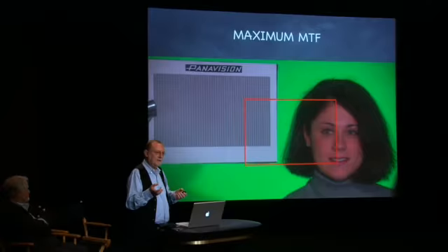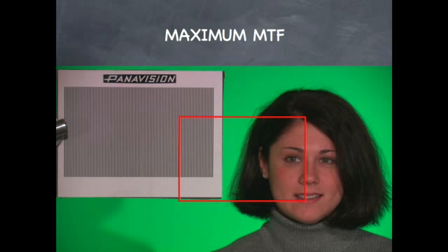These were high-resolution images. Obviously, for the projector, we're only using a part of the image, but I wanted to show you practically what this means. Now, when it says maximum MTF on this particular lens, this is 2/3 inch, and I believe the MTF was actually about 75% at 50 cycles per millimeter, which is one of the issues we'll get back to in a bit, because the smaller the sensor, the higher the frequency response necessary, which is at odds with what the camera manufacturers are doing, because they keep using smaller and smaller sensors and then saying to Canon, make a lens for this. And of course, the electronics guys love it because it makes the sensors cheaper, because the yield on a CCD varies as a square of the area on the wafer, but it's simply impossible to get high contrast in these little tiny handycam type cameras.